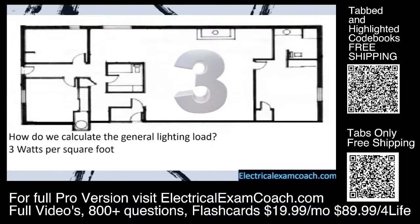So for all of the general lighting and all of the general receptacles, all we have to do is take the square footage of the dwelling unit and multiply it by 3. But the code language actually uses VAs. So 3 watts per square foot or 3 VAs per square foot.